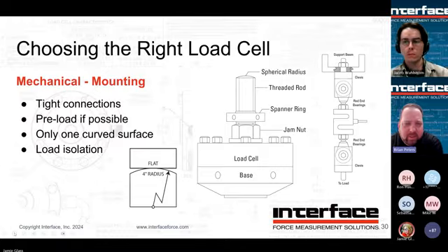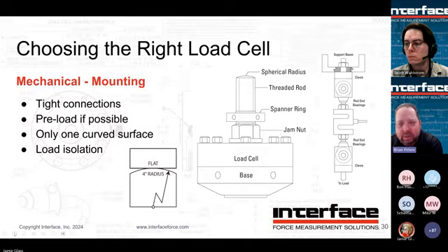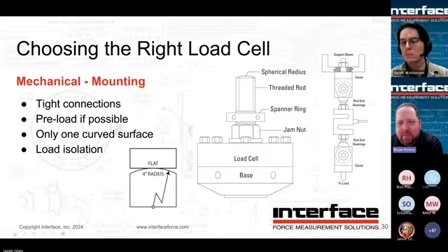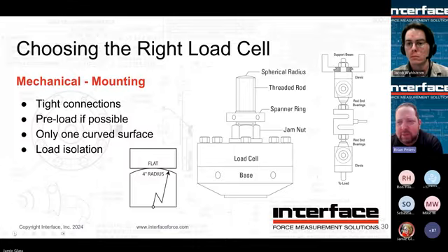on the top. So you'd want to have a flat surface interacting with that as depicted on the picture on the left. Our cal grade sensors come with pre-installed cal adapters, which oftentimes customers don't notice, but the tops are actually spherical. So you have the choice of loading through the threads or directly on the end of that if it's compression only if you want to. But basic test setup is well depicted on the right with essentially some rod end bearings to decouple the sensor from any potential side or bending loads. May not be able to do that, but that would be the preferred setup, of course. And that way you ensure that the only loads going through the sensor and through the bridge are going to be axial in nature.